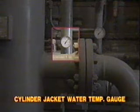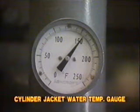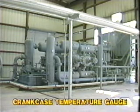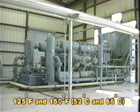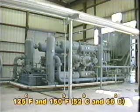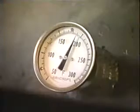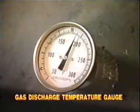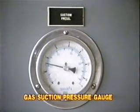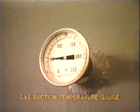The cylinder jacket water temperature gauge indicates the temperature of the water in the cylinder jackets. The crankcase temperature gauge registers the temperature of the oil in the crankcase. Normally, this is between 125 degrees Fahrenheit and 150 degrees Fahrenheit. The gas discharge pressure gauge shows you the pressure of the discharge gas, while the gas discharge temperature gauge indicates its temperature. The gas suction pressure gauge registers the pressure of gas entering the cylinder, while the gas suction temperature gauge shows its temperature.